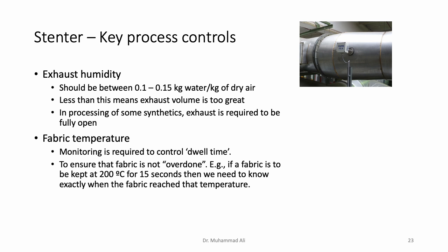If the fabric is getting more dwell time than what is required, then we can increase the machine speed of the stenter. If the fabric is getting less dwell time than what is required, then we have to reduce the speed of the stenter so that the fabric spends a longer duration inside the treatment chambers.